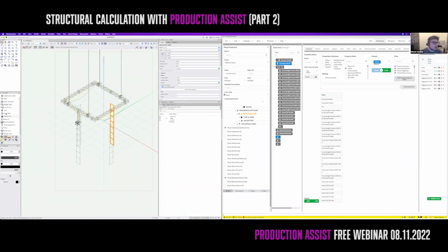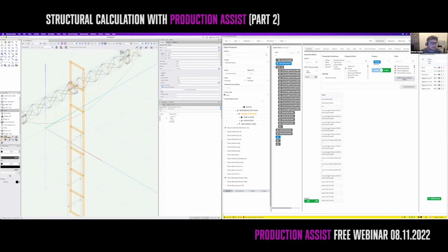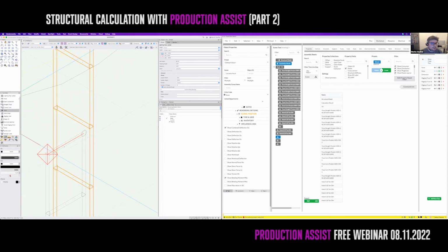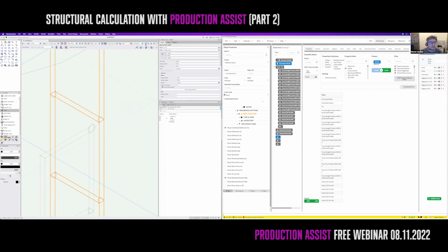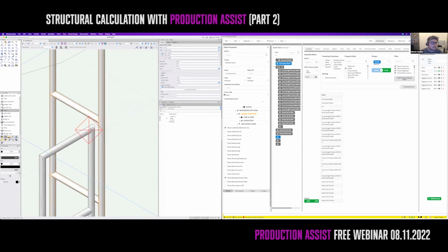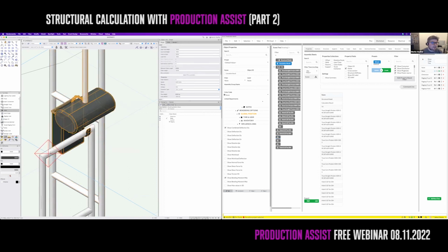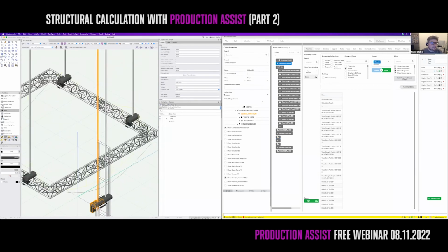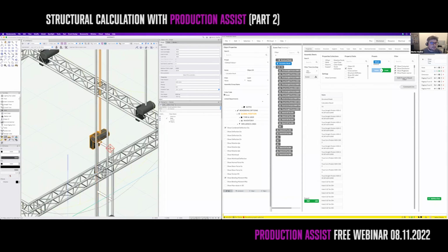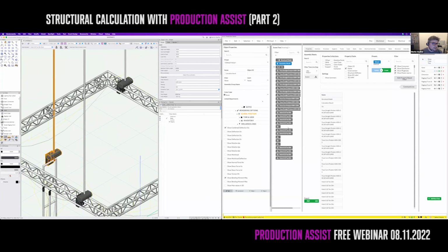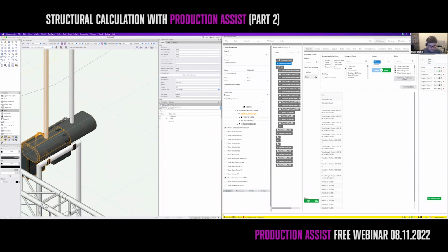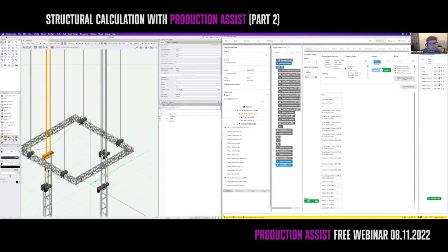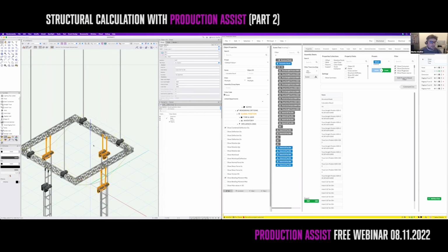Again, I will put in more hoists so that I have the proper reports for this. So clicking in here, clicking. Sometimes it's a little bit challenging with the snapping, then it's easier to use the shading mode. Inserting in here, inserting in here, inserting in here, inserting it here, inserting it here, and, wait, move more to it, inserting it here. I'm selecting all the drops that I want to use for this. And again, set the high hook to 0 so that it's connected with the actual system in here.